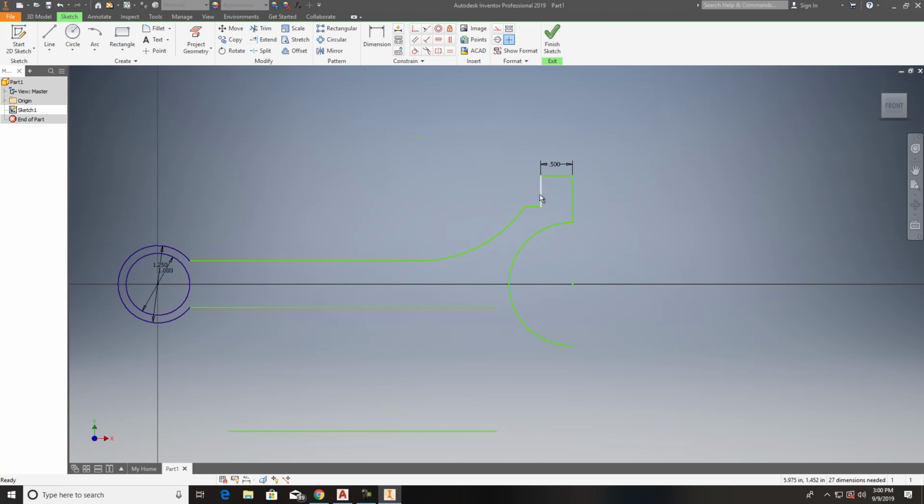So what I do, I want to grab this, I'm going to hit my control tab, click on these, click this, and click this. I want to do a mirror. Mirror line. I don't have a line, so I'll have to go in there and add myself one just to the center of it. I got a little line there now. So it's back to the drawing board again with the mirror. Just come up here and grab all this stuff that you want to keep. My mirror line is this, apply, and done.